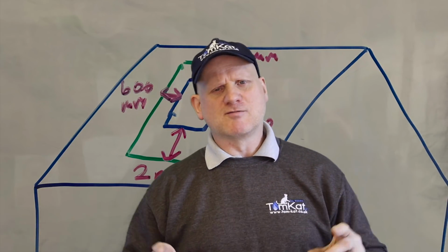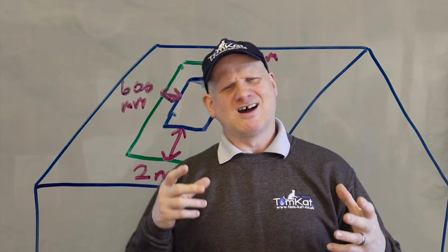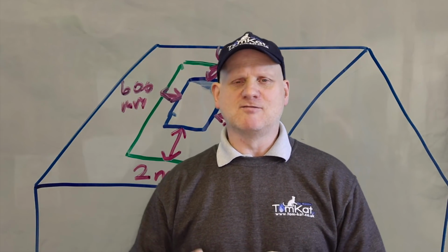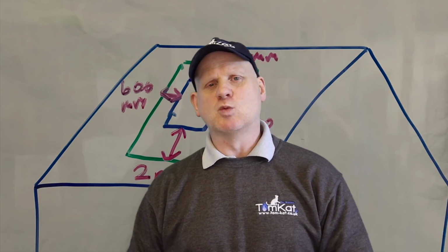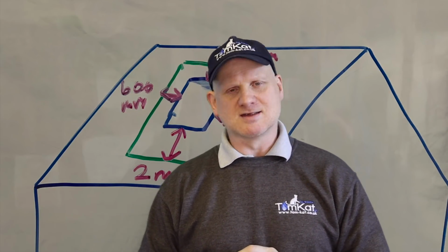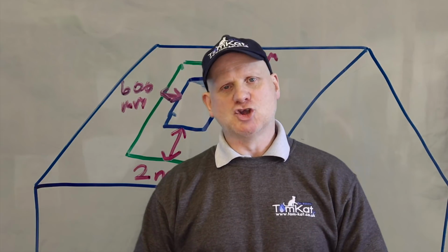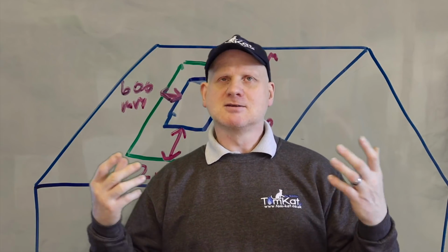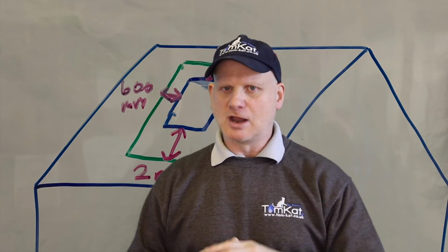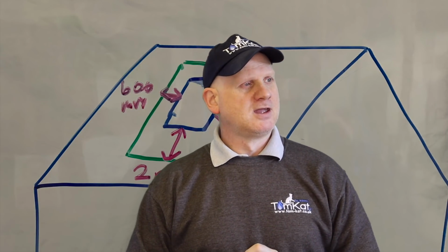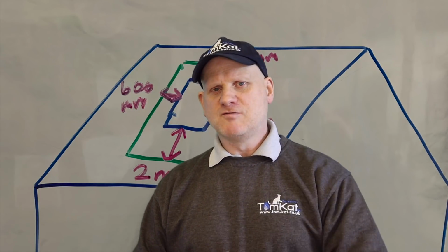And the other problem we've got is dormers. On average, most vertical flues need to be at least 1.5 meters away from a dormer window. And again, manufacturer's instructions will help you on the way with that. Now, before we move on to